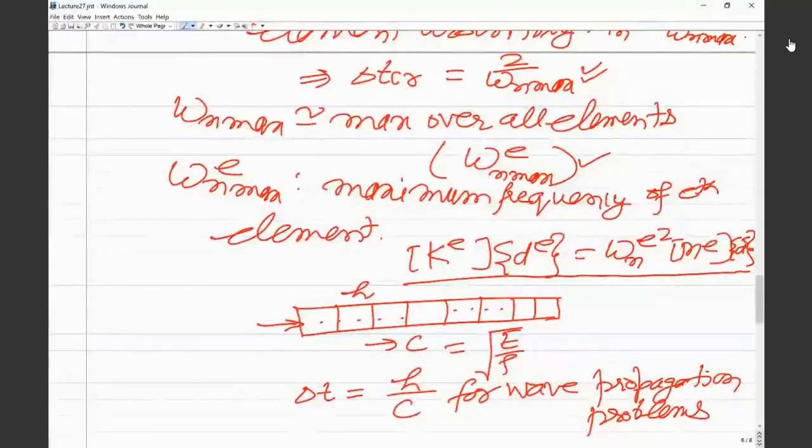Yeah, but usually you find that omega n max will be smaller than or equal to omega n max E, which is without any boundary conditions, because the highest natural frequency of each element will be either more than or equal to omega n max.